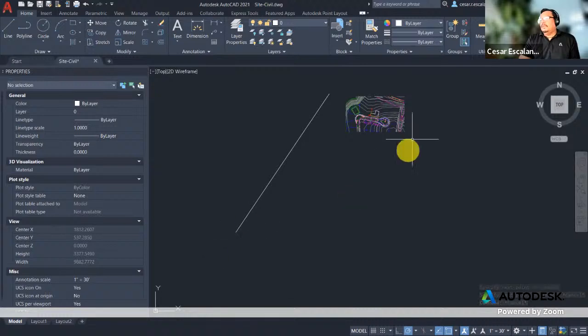This just happened to be very close to the site. But when you're actually in a survey file, the point references are typically associated with state planes. And sometimes the 0, 0 is 6 million feet away from the site. And so that's not a good 0, 0 to use, right?